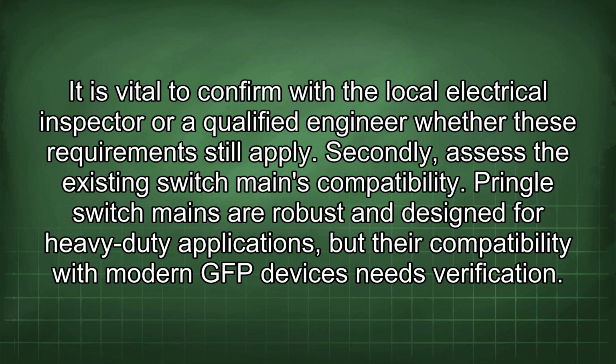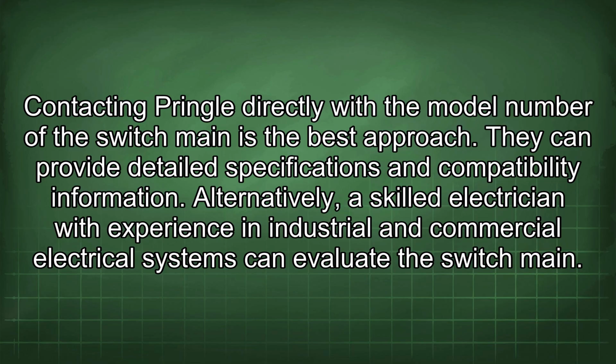Secondly, assess the existing switch main's compatibility. Pringle switch mains are robust and designed for heavy-duty applications, but their compatibility with modern GFP devices needs verification. Contacting Pringle directly with the model number of the switch main is the best approach. They can provide detailed specifications and compatibility information. Alternatively, a skilled electrician with experience in industrial and commercial electrical systems can evaluate the switch main.